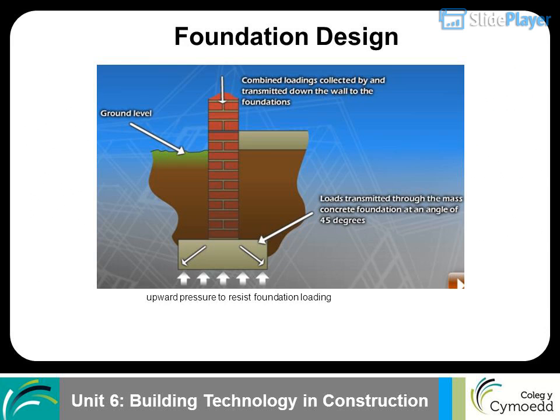Foundation design. The function of any foundation is to safely sustain and transmit to the ground on which it rests the combined dead, imposed and wind loads in such a manner as not to cause any settlement or movement which would impair the stability or cause damage to any part of a building. The subsoil beneath the foundation is compressed and reacts by exerting an upward pressure to resist foundation loading.